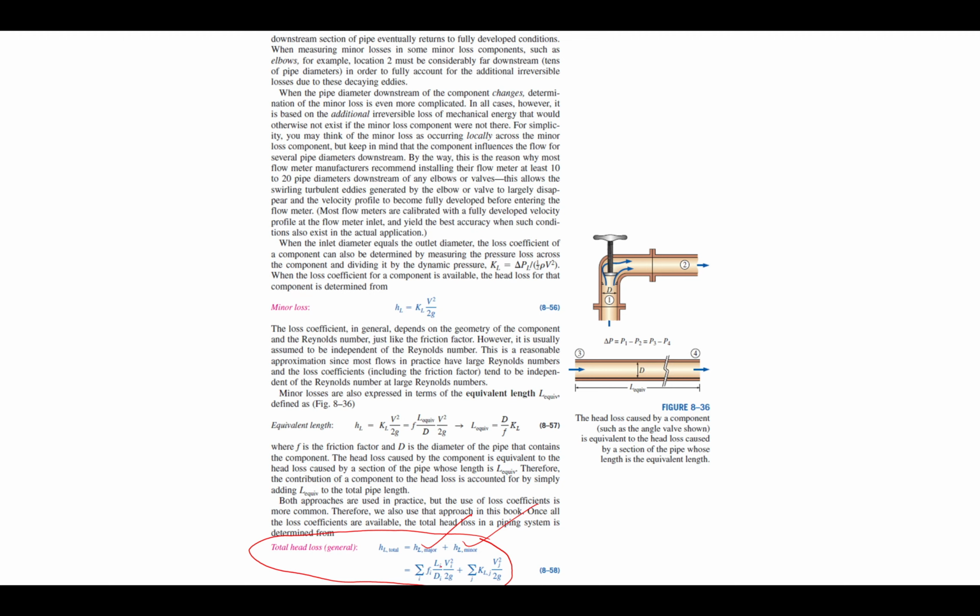You can calculate the major loss using the summation, where I indicates the pipe, whether you are going for one pipe, two pipes, or three pipes; at the place of I you put 1, 2, 3 and add. So in a single pipe like that, this pipe has the major loss due to roughness, and due to this bend there will be a minor loss. So you will also calculate the minor loss.